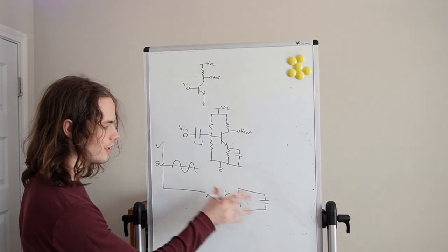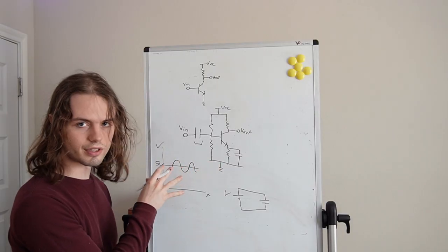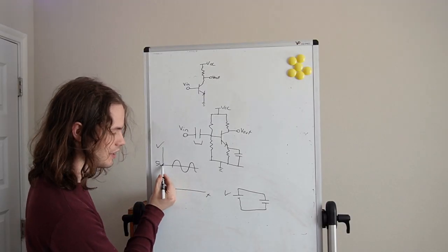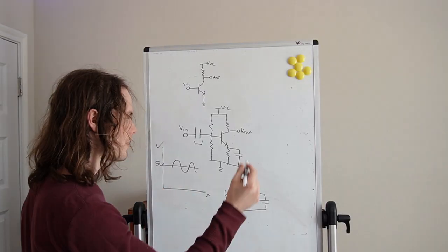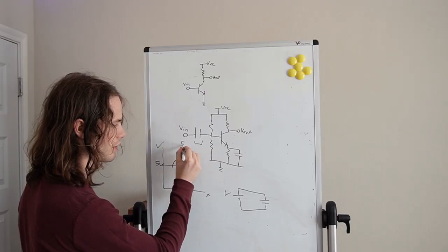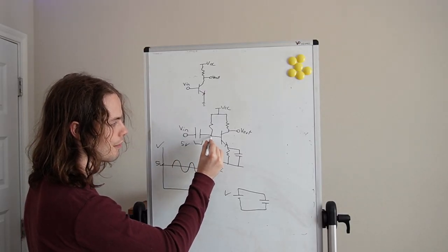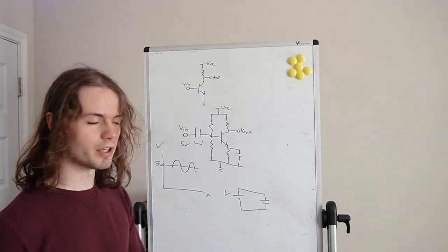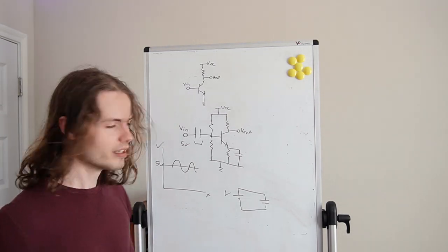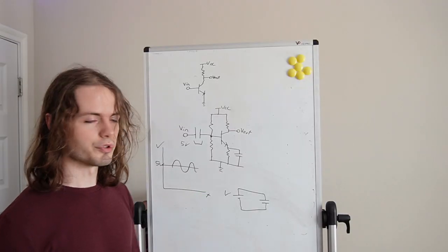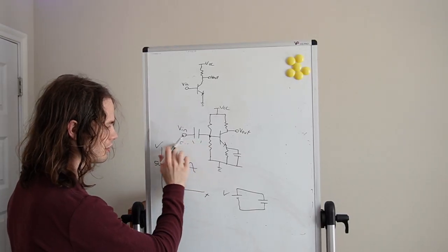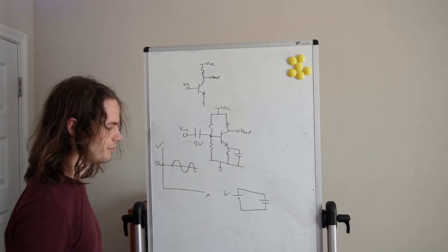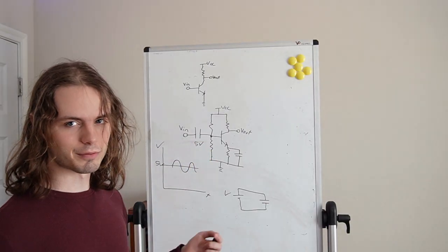So if we bring that over here and you ignore the AC fluctuations, the capacitor will charge up to whatever DC voltage is here. Well, it'll be the DC voltage here, which let's say was 5 volts, minus whatever voltage is at this node here. So it may not be 5 volts, but for now let's just say this is ground and that it is 5 volts. So this capacitor will charge up to 5 volts. Again, that's not what actually happens, but for simplicity.